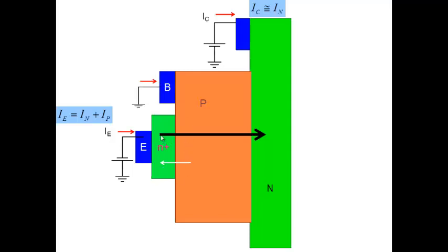And we are saying that all the electrons go into the collector, but some may recombine here. A very, very small fraction may recombine here. And therefore, when an electron recombines with a hole, one hole is lost. So the base current has to supply the hole which is lost also, right? But base current is primarily equal to this current here, IP. So that's the relationship between the different currents that you see here. Emitter current is made up of both of them. Base current is made up of the holes which are injected, and collector current, of course, is this IN.